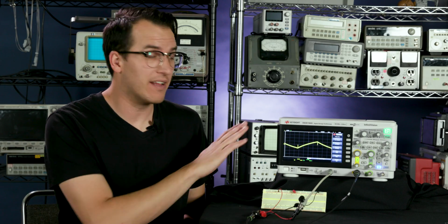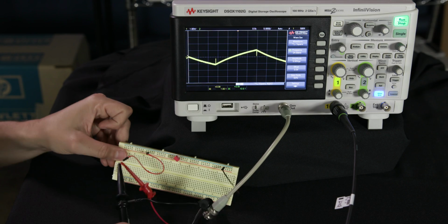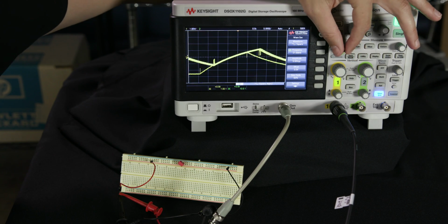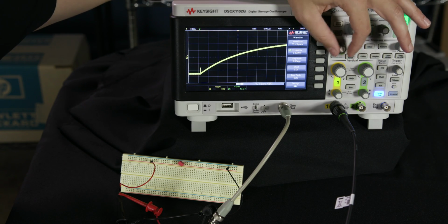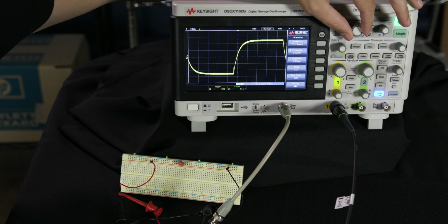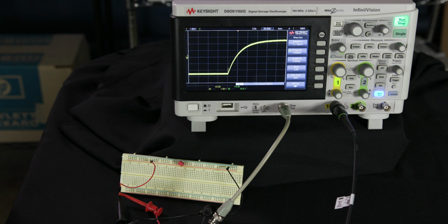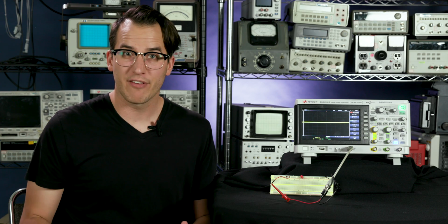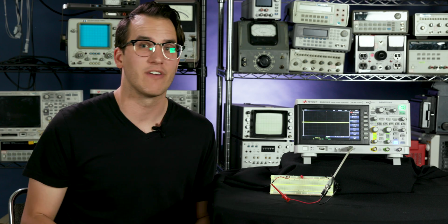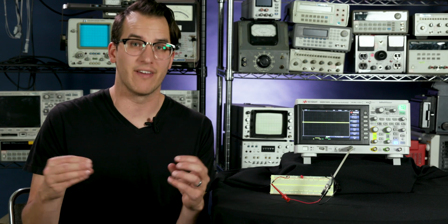So let's go back to our circuit and the oscilloscope. So you can see all these wires are that inductance we modeled on the whiteboard. I'm going to drop the frequency down a little bit so we can look at this a little more clearly. We can still see that I have a glitch on the screen. I also want to point out real quick, there's a formula that lets you calculate the inductance of a wire based on its length and width.